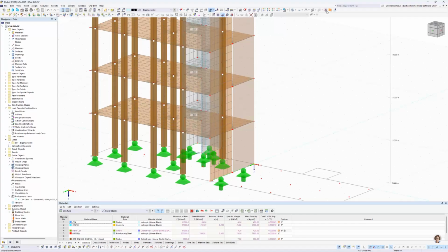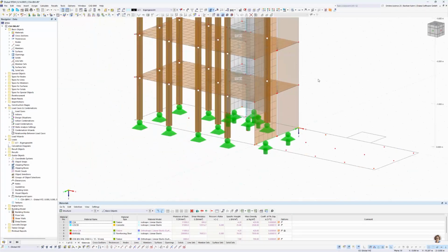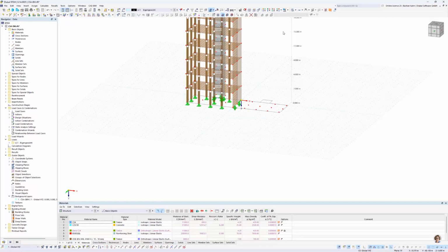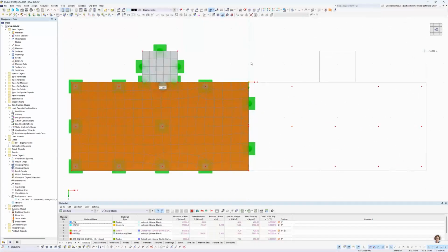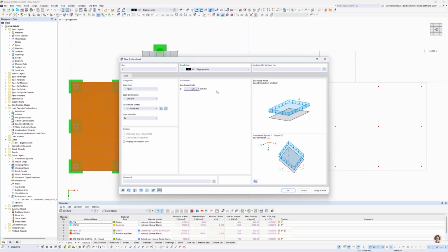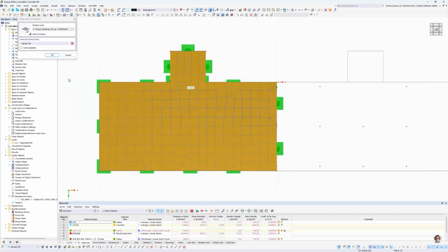We do not see a mesh here. Why? Because we have not displayed the timber frame wall on it. But here it is. And loading we put on top of it. So we go in fly mode again. And what load we want to have on it is 3.4 kilonewton per square meter. There. And that should be this. No, this one not. Red one. From left to right. Okay.